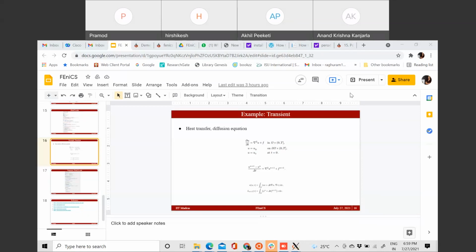Okay. So you are just doing a standard phase field kind of thing. You don't do anything special when you go across material boundaries. So you do as you would do for a homogeneous material. Yeah. As of now, we do the same, but we have also proposed another way. We can reduce the fracture toughness of the interface, so that we can grow the crack along the interface, and then we can explain the branching phenomena. But that is in the framework of phase field.